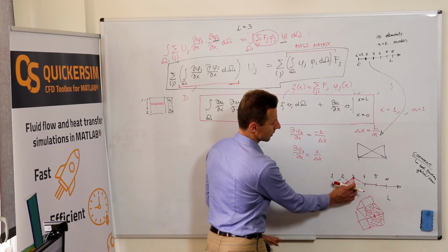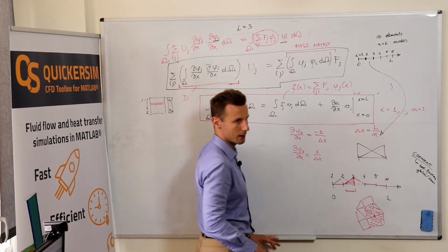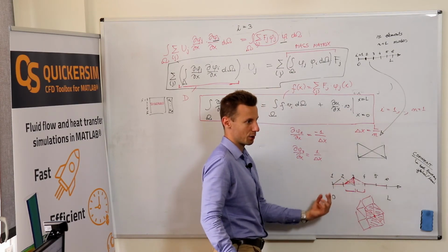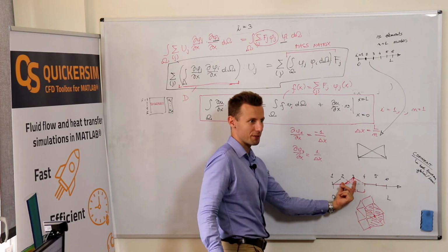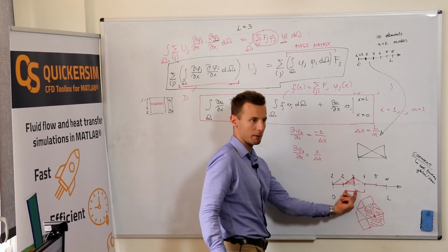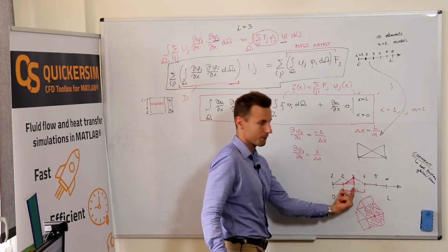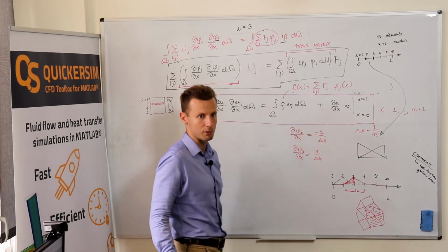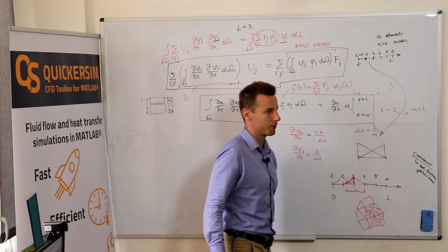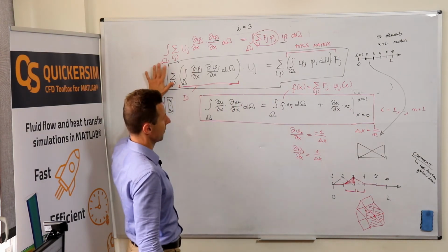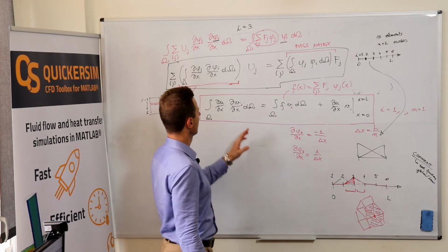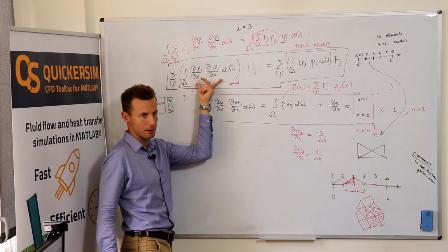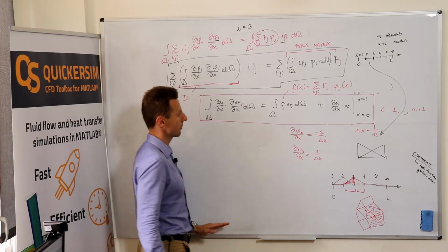So then we start looking at this element, and in a minute we will need to look at this element to complete the integration of the third test function, because integrating in this element means actually only taking the half of the contribution, but then we need to move to that equation and also integrate the third test function over the area of the adjacent element to really fulfill this equation. So it's much easier to define local matrices for each element and then assemble the algebraic system of equations.